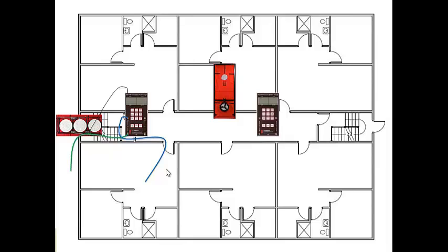Then we're going to use the fan control cable, because we're going to use cruise, and we're going to connect that. Let's say this is a big enough building where we need 3 fans to get it up to pressure. We're going to connect that fan control cable to the top fan, and we're going to run 2 fans wide open, and then we're going to cruise the speed on the top fan to keep it at 50 pascals while we're going around unit by unit. So that's how we want to set up and do that test.